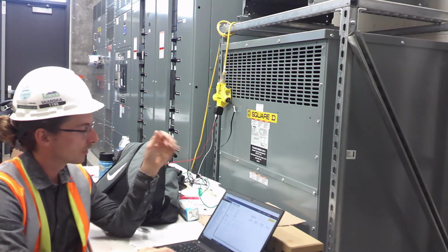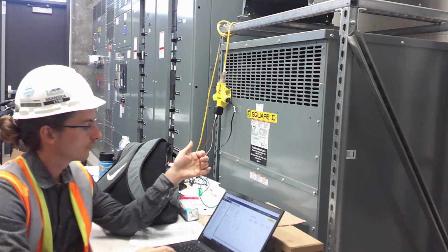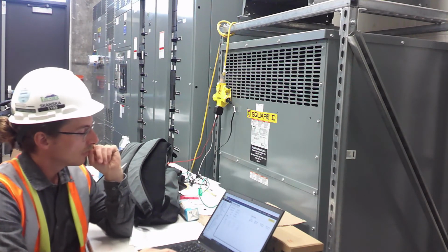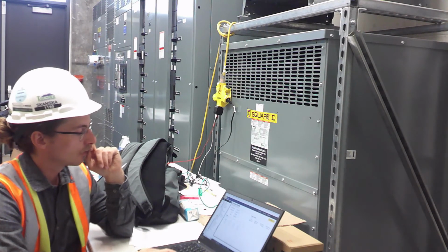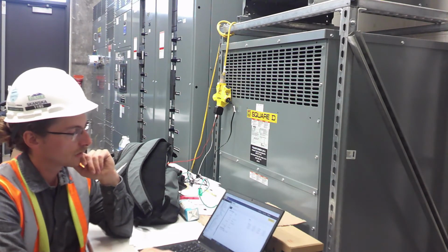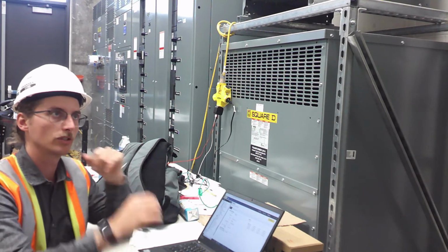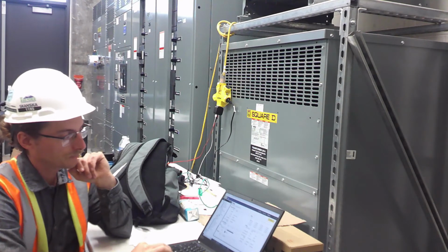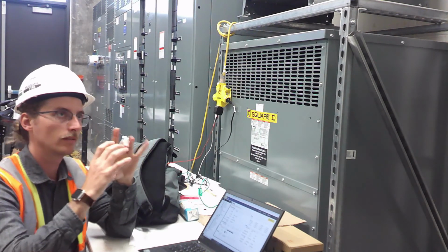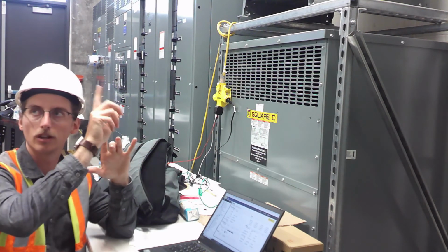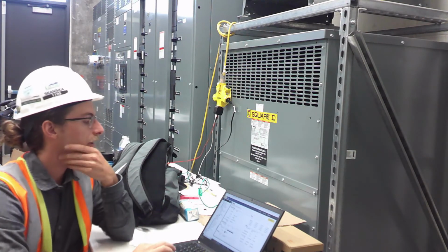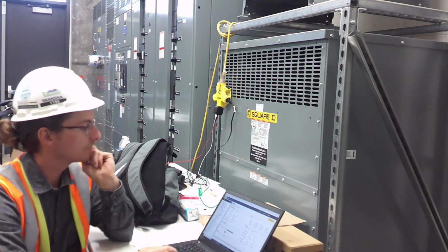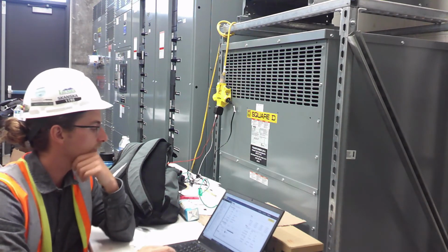So those rooms are all labeled like RR, whatever the number is, RR200E. You'll see on here, this one, there's no switch in there. There's only the aux sensor input, which is that switch itself. Those are all set up to work on occupancy, so that when that switch goes active and sends the signal back, it kicks on the lights. And it goes off at a predetermined time, right, 10 minutes or 20 minutes or something? Yeah, exactly.